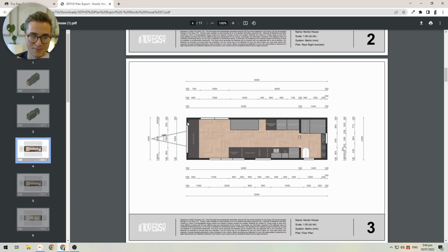So this shows you the distance between interior and exterior walls. This is a 100 mm exterior wall. Then you've got a huge gap, and then you've got another 100 mm interior wall in this case, and then you have a 1.4 meter space for your interior bathroom here, of course. And then you will see the 800 millimeters for this interior wall here, another 800 millimeters for your interior door, and then another 600 millimeters for your last wall panel here.